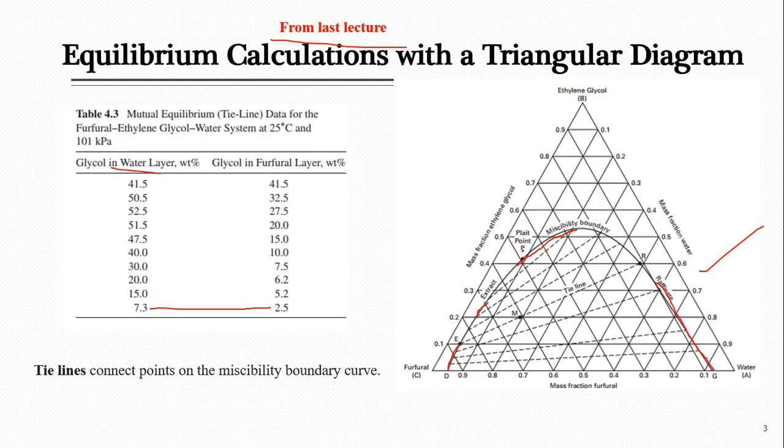From which point? This plate point is the separating point. If you look on the right side of this, we have raffinate here, and if you look on the left side, we have extract. Actually if you just switch the main location of water and furfural, then this will just shift. It is not necessary always to be located on the left and right of the plate point.